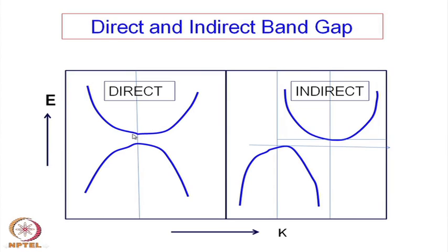And this is the characteristic band gap. Normally, if we have to draw a band diagram of this solid, we will draw a horizontal line like this and another horizontal line here. Okay. So, that will represent the band gap for this material. Here also we have just drawn two horizontal lines, one is this one and there is this one, and this is the band gap. So, we do not draw a curve, and we are not concerned about what the gap is away from their maxima or minima.